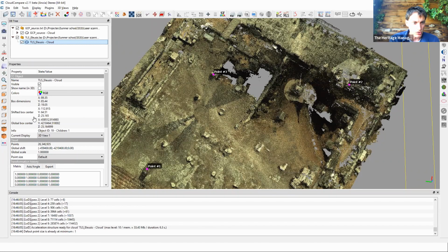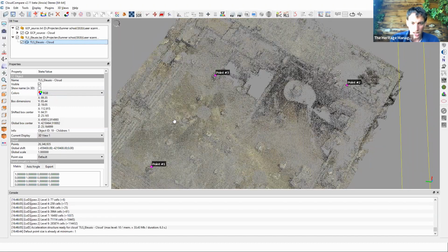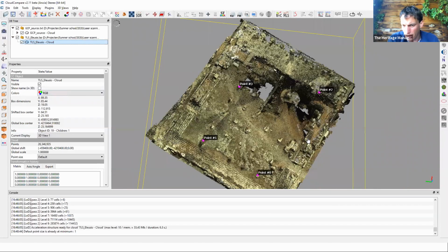You get some geometrical information about the dimensions of your point cloud. So you have here an XYZ dimension. So I have a point cloud. The bounding box is actually here the green area that I have around my point cloud, and it has a dimension of almost 90 by 90 meters and a height of almost 20 meters, 19 meters. This is the parameter of the global shift, so the value that we used while loading the point cloud. And these are the local coordinates, so not the absolute coordinates, of the center of our box. So it's actually just half of these box dimensions.